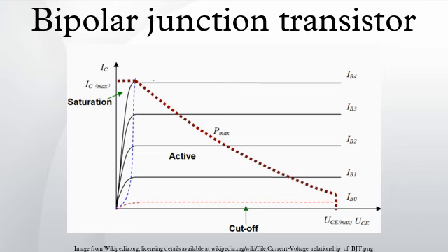Narrowing of the base width has two consequences. There is a lesser chance for recombination within the smaller base region. The charge gradient is increased across the base, and consequently, the current of minority carriers injected across the emitter junction increases. Both factors increase the collector or output current of the transistor in response to an increase in the collector-base voltage.